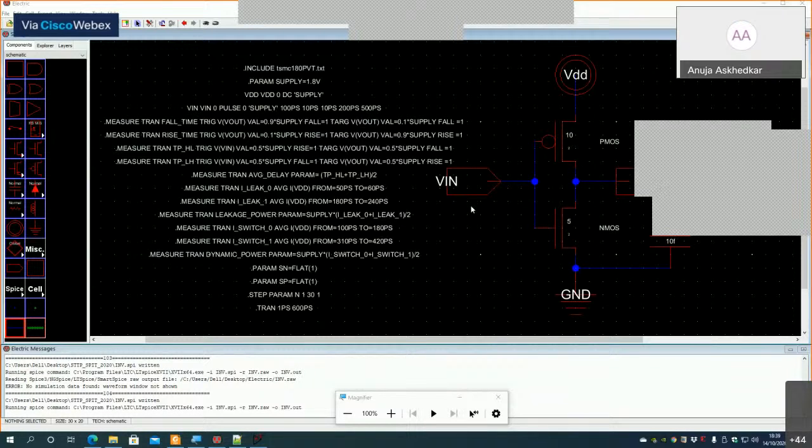See, the results that we are getting are from LTspice, not from Electric, because the SPICE includes LTspice. Actually, whatever analysis, one thing I shall make clear, maybe some of you may be having doubt that these simulations, these commands we can write in LTspice and we can directly use only LTspice and do the simulation. You are right. For now, whatever simulations we have done, we do not essentially need Electric. But I decided to use Electric.